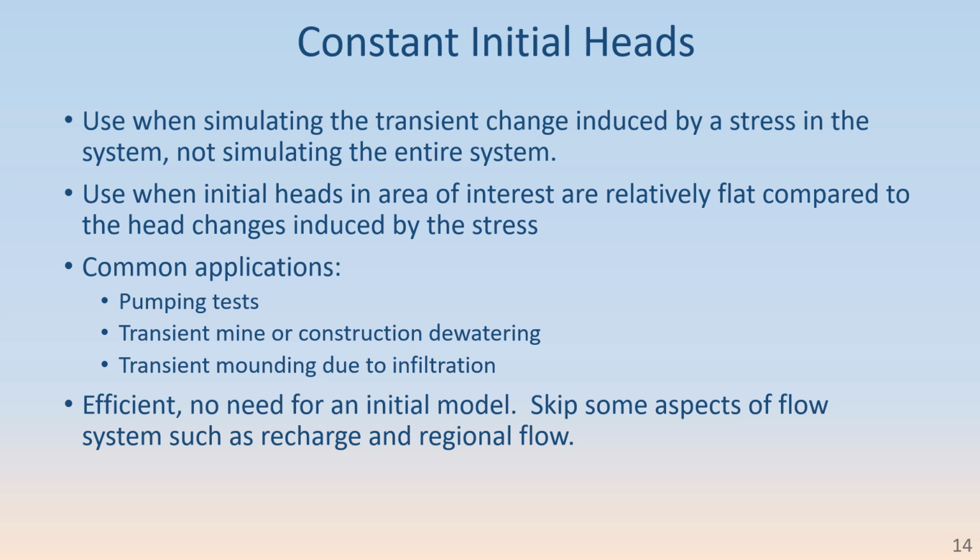And this turns out is exactly fine in a linear or unconfined domain situation, because those two models can be superpositioned perfectly. And it's approximately fine in other situations with, say, nonlinear domains like unconfined. When you do a standard pumping test analysis, say the Theis solution or Hantush solution or Neuman for unconfined, you're making that same assumption.